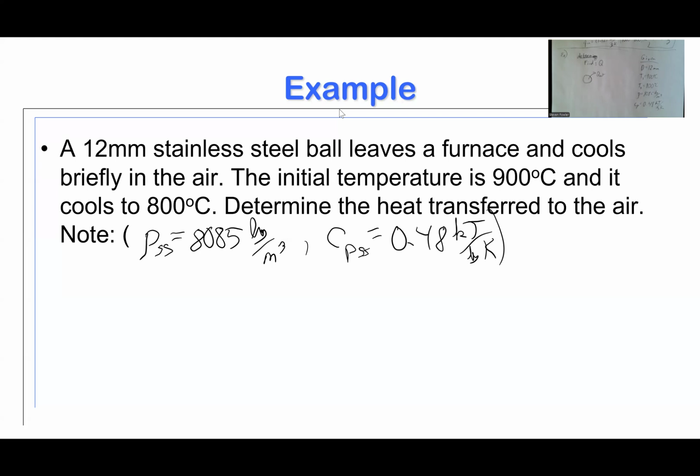It's probably moving at a constant speed, so there's no change in kinetic energy, and they've not said anything about potential energy. The main energy going on here is going to be this heat transfer. So I can write my first law just simply from that. Again, add your ins, subtract your outs. That means minus Q out is going to equal the change in the energy for the system. Assuming that it's moving at the same speed as it comes out of the oven and at a relatively constant elevation, the only energy changing on the right-hand side is going to be delta U.